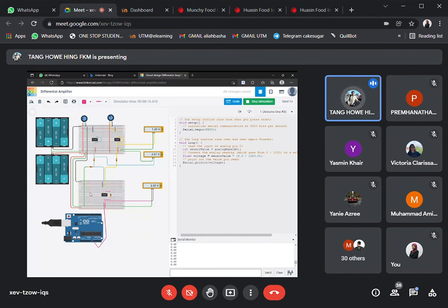But for the Arduino Uno, you can see that the electricity comes from the batteries, goes to the voltage followers, then goes into the differential amplifier output, and then it enters the Arduino Uno board. Then later on, it goes nowhere. It is not going to return back to the battery. So that's why the reading over here just keeps on giving you 0.